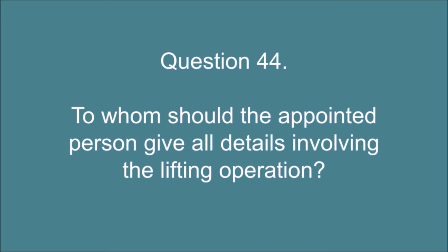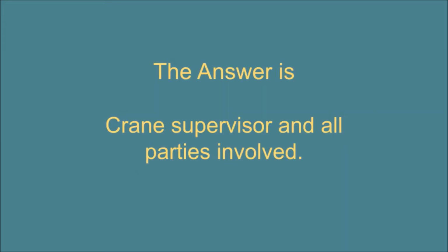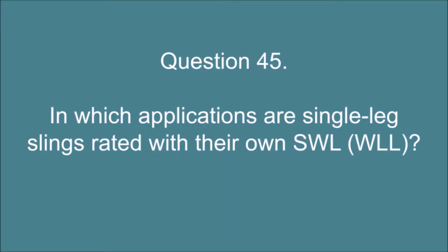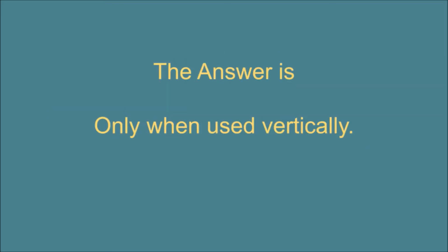Question 44. To whom should the appointed person give all details involving the lifting operation? The answer is crane supervisor and all parties involved. Question 45. In which applications are single leg slings rated with their own SWL, WLL? The answer is only when used vertically.